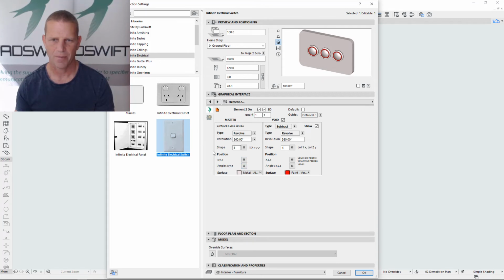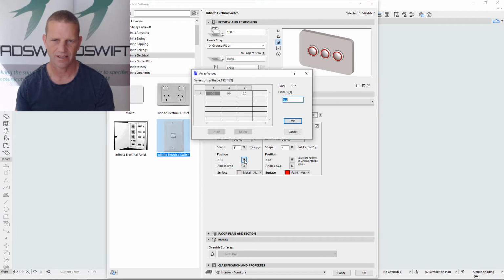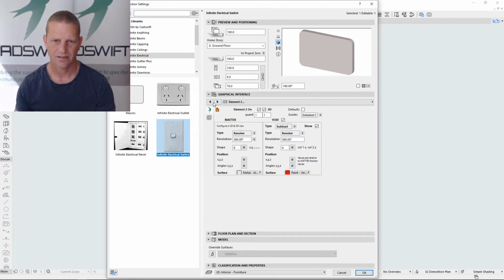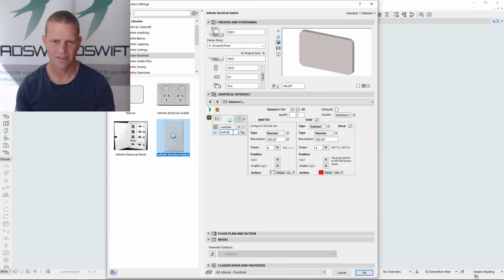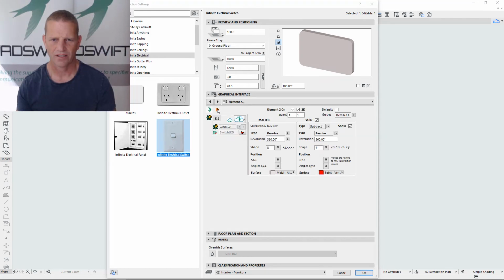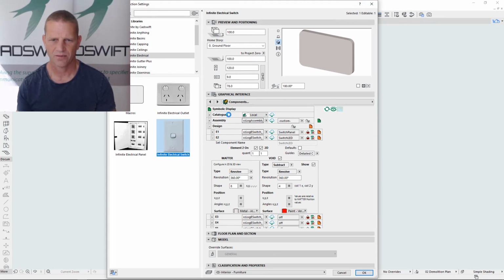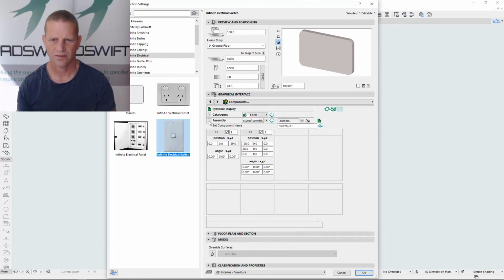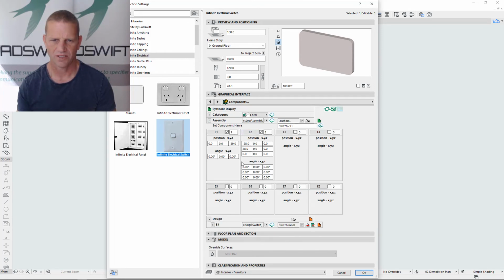however, that positioning really should be handled at the assembly level. So if we go back to here, that should really be set to 0. Then we go into here, and we save this as switch LED, upload, download, and lock. Now we'll go back to the assembly page, and we'll go into our assembly, and we'll position them here.